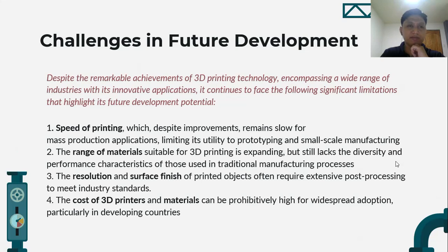Challenges in future development. Despite the remarkable achievements of 3D printing technology, encompassing a wide range of industries with its innovative applications, it continues to face the following significant limitations. First is the speed of printing, which, despite improvements, remains slow for mass production applications. Second is the range of materials suitable for 3D printing. It still lacks the diversity and performance characteristics of those used in traditional manufacturing processes, since the most common 3D printing materials are PLA or polylactic acid, and also ABS.